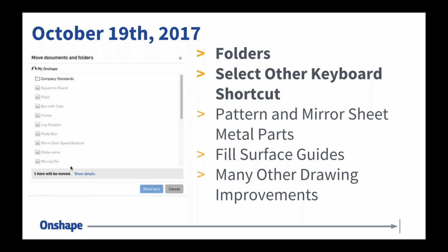Now, as with the past improvements for quite a long time now, there's a lot in drawings that was added with this update. Unfortunately, we just don't have tons of time to get into it, but I will try and point out a few of the important ones. In my opinion, the big one for drawings in this update is the ability to copy or duplicate a drawing. Duplicate's a better word for it. So you can take an existing drawing, right-click, and duplicate it. Great if you want to make small variations of drawings. And you can also duplicate assemblies, by the way, as well. I do want to mention that.